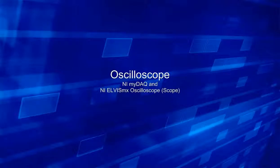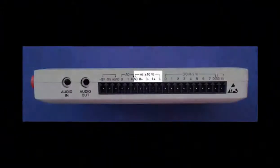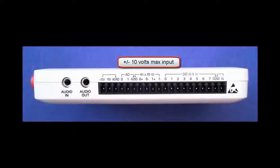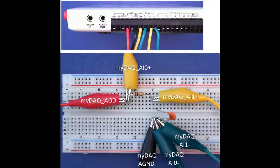Let's learn how to use NI myDAQ as an oscilloscope. As we're getting started here, recognize that the two analog inputs are limited to plus and minus 10 volts maximum input. Do not exceed that range of plus or minus 10 volts.